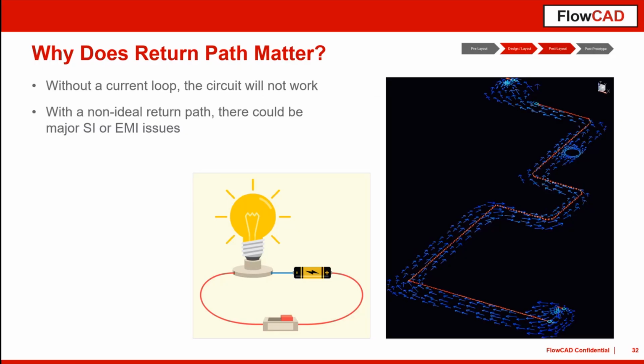The background of this return path analysis is, in principle, once we have high-speed signals, what is high speed? Let's say signals starting at 50 megahertz or even a little bit lower, and of course, that never stops in the frequency range. The return path is directly located underneath your signal trace.